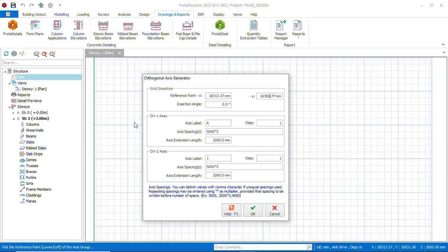So now in my horizontal direction, based on the architectural drawing or based on how I want to position my columns, I want to position that at interval of 5 meters, but then the length of this building is 30 meters. So 5 meters, and I have them in 6 places. So if the distance is not the same, let's say we have 5 meters, we have 4 meters, then you have to be entering the distances. You enter this, you give space, you enter, you give space. Okay, then the width is 10 meters, then it's just in 2 places. So when you're done, you click OK.